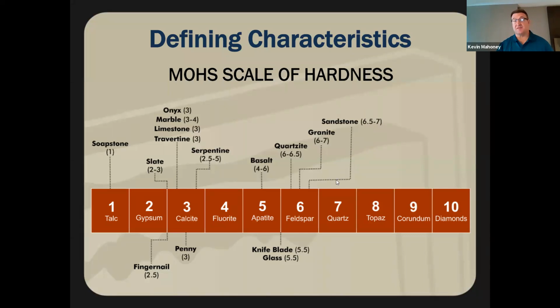You can see here that sandstone has a very high Mohs hardness scale compared to its counterparts, but for example, a light commercial rating with a honed finish in a commercial application on a floor can scratch. And I'm telling you that because I've lived through it, and the expectations of that stone didn't live up to what the architect wanted when he specified that in an apartment complex lobby. We wound up with scratches and some hurt feelings because it didn't perform like he wanted it to. So it's always great to ask, how is this going to perform in the environment? Given our druthers, we probably would have said, hey, that's not the product for you. We'd rather not have the sale and have a relationship going forward.